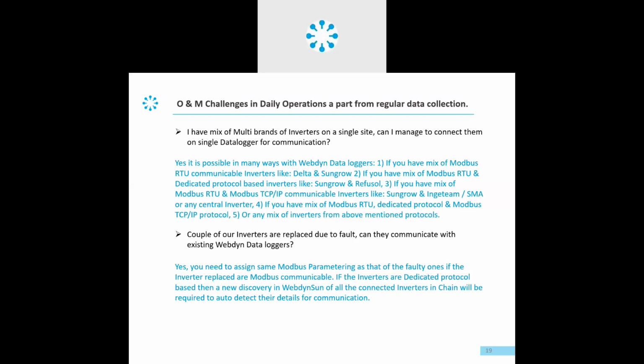Yes, there are several different ports for Modbus RTU and Modbus TCP/IP. For Modbus TCP/IP, there is a dedicated RJ45 Ethernet port, which is multi-usable: to provide the internet to the data logger and also to communicate with the field devices. And for Modbus RTU, there is a separate port, which is normally termed RS485. I'll show you the physical connections in the pictures in the further slides.